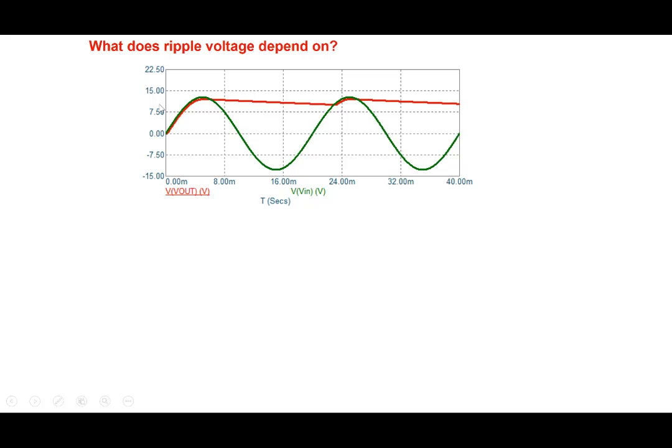All right, so the ripple is something that we don't really want, and the ripple frequency is at the input frequency that you see here. This DC voltage is going to power lots of devices, and this ripple can get into the circuit and cause unwanted effects, and can get amplified also.